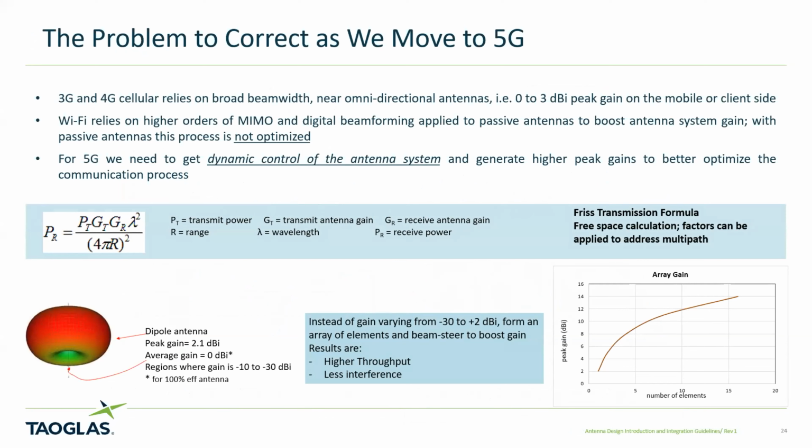Third up is beam steering, and as I said, implemented correctly, that should quite often provide the most benefit of the 3 active antenna techniques. The reason is, and I hate to say this because I've been an antenna engineer my whole career, but unfortunately, in a cellular-based client device, probably the most inefficient component is the antenna. If I have a smartphone and I initiate a phone call, that smartphone is going to connect with a single base station. When I transmit a signal out of my smartphone, I am blasting my quarter, half, or 0.6 watts over a very wide angular region, not at the intended direction on the other end of the link. So it's a very inefficient process.